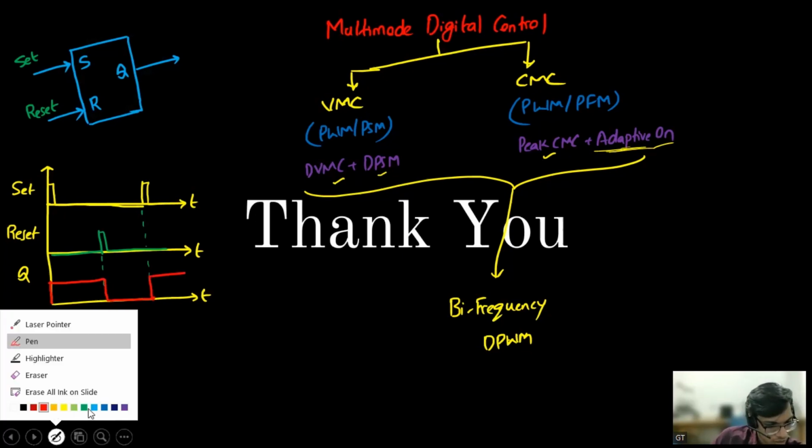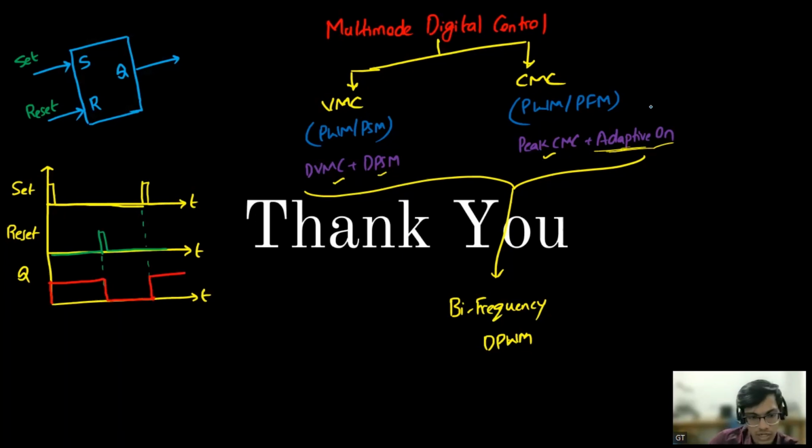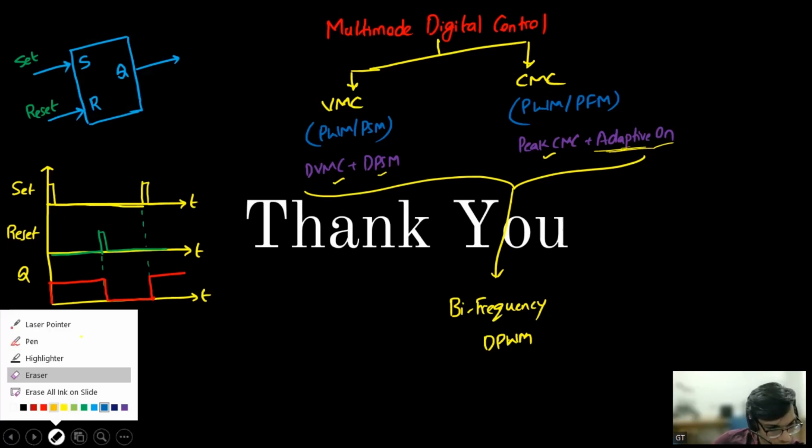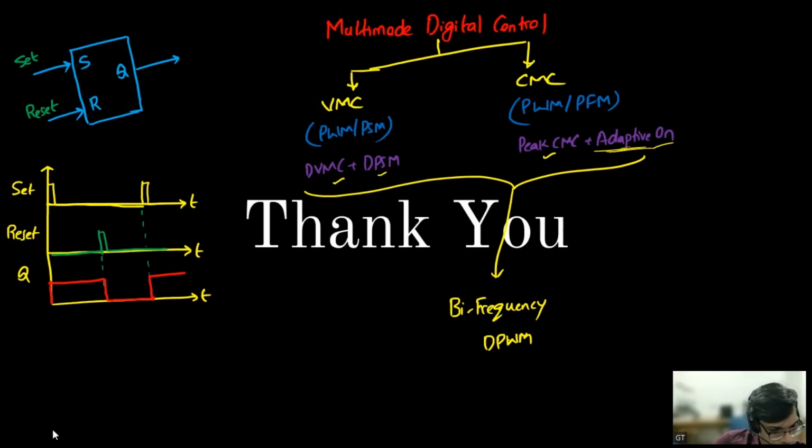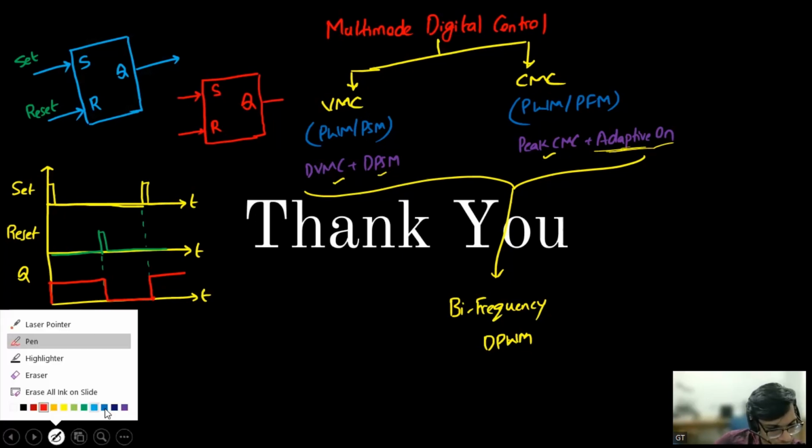Yeah. Now there is a slight modification and I'll draw something like this. I need more space, so I'll draw something below that. So this is my set, this is my reset, this is my Q. And what I'm doing now is I'll give the set pulse to reset and the reset pulse to set, and let me check what will happen.